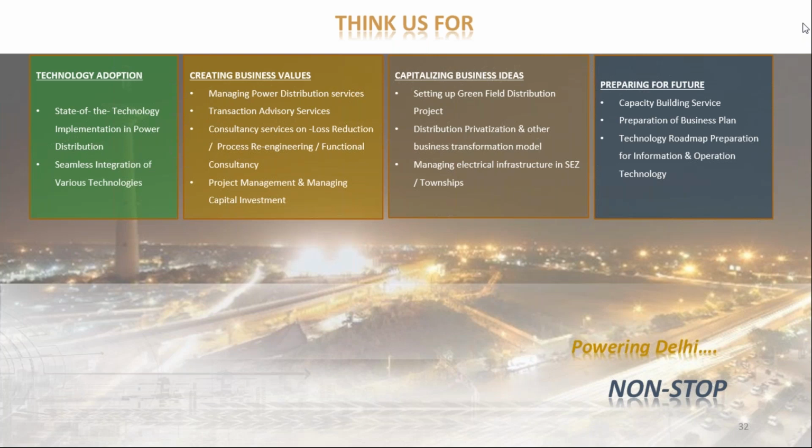Okay. So in India, we have the BIS, Bureau of Indian Standards, and they have defined the rating for appliances. So if a 5-star appliance is there, its energy consumption is almost 40-50% of a normal appliance, and those star ratings come for all appliances like refrigerator, air conditioner, and even the transformers which we use. The regulator has said that you should use not less than 3-star rated transformers, because in those transformers the loss level for a particular capacity is less.